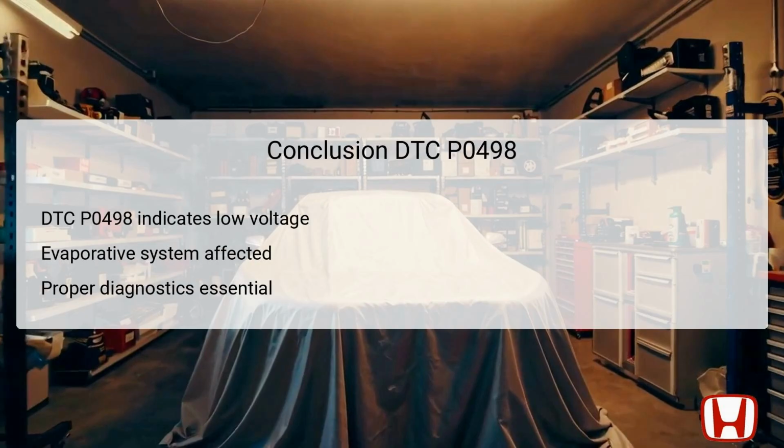In conclusion, DTC P0498 signifies a low-voltage condition in the EVAP canister vent shut valve circuit of Honda Civic models from 2006 to 2011. Understanding this code and its implications allows technicians to address crucial issues within the evaporative system efficiently. Proper diagnostics, as outlined in this troubleshooting guide, are essential to uncover the root causes, whether they stem from wiring issues, component failures, or ECM malfunctions.